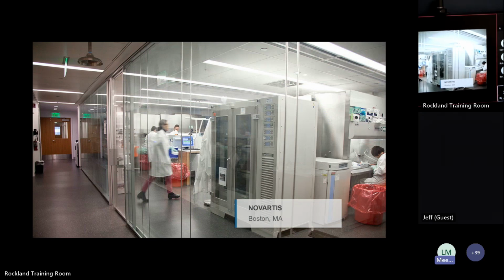This was a project here locally we did several years ago. These particular units are the 12-inch wide linear unit, and it's actually right next to the luminaire, the lighting system within that 2-foot grid. If only there was a chilled beam with lights integrated into it. Stay tuned. There is. But you can see that these are actually located above the fume hoods. So we have fume hoods in this case, but just making sure that, again, if they are above the fume hoods, that there's absolutely no collisions, or opportunities to move airflow across those sashes.